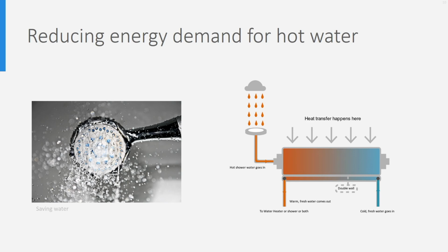A heat recovery system for a shower works in a similar way, but instead of using air, it uses the water. If you're showering, the water that ends up in the gutter is still warm. This wastewater is led along the supply water, which will warm it up, and therefore less hot water is needed to achieve the desired temperature.